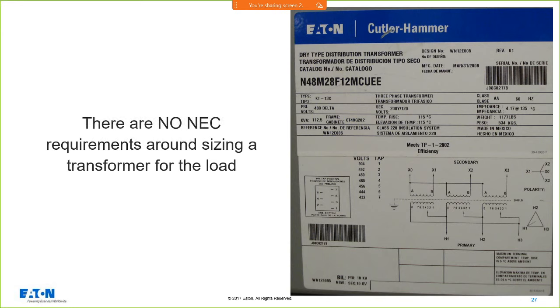There is no NEC requirement around sizing a transformer for the load. We have requirements that say you need to have the right size conductor. We have requirements that say you have to have a generator to supply the load.